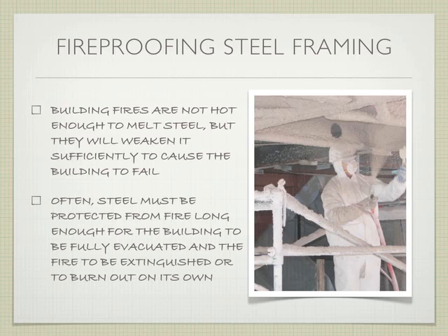But it was just enough for these trusses, and recognize because it was trusses, the members themselves are smaller, right? And because those members are slightly smaller, it takes less heat to heat them up to the point where they start to weaken, right? So go up to the floor, and I forget what floor it was that got hit. Go up to that floor, right? The combination of the jet fuel, right? The combination of a little bit of this fireproofing being knocked off, right? Caused some of those trusses to start to fail, right?